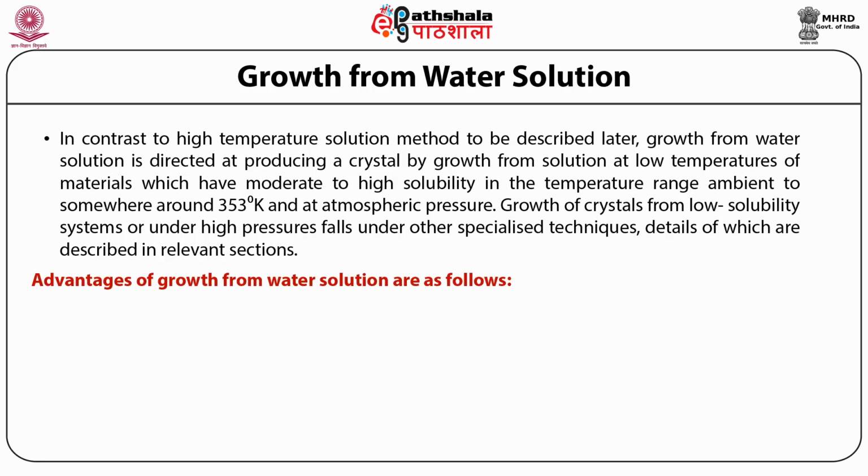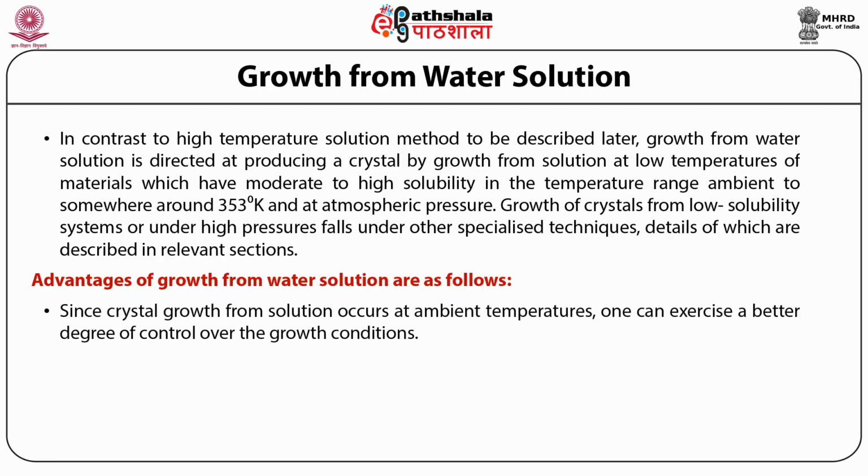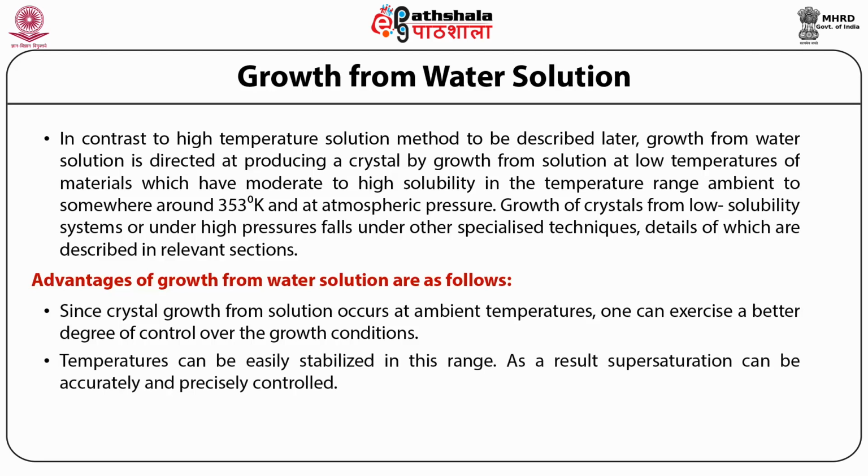Advantages of growth from water solution are as follows. Number one, since crystal growth from solution occurs at ambient temperatures, one can exercise a better degree of control over the growth conditions. Number two, temperatures can be easily stabilized in this range. As a result, supersaturation can be accurately and precisely controlled.